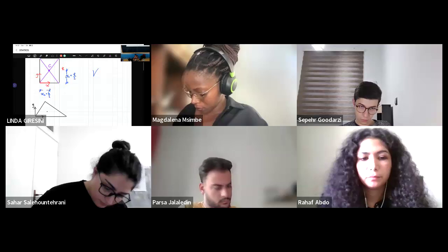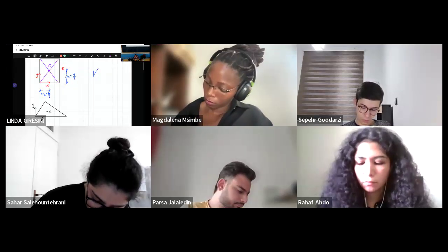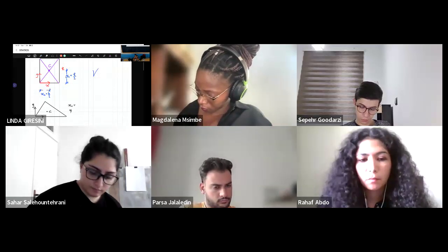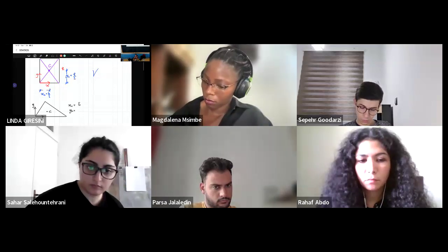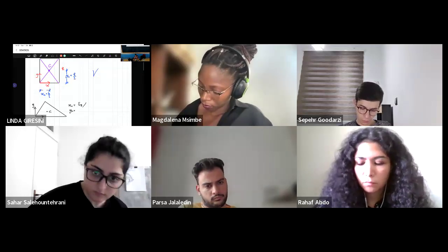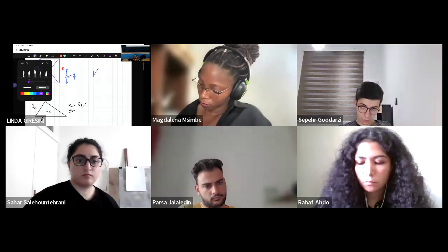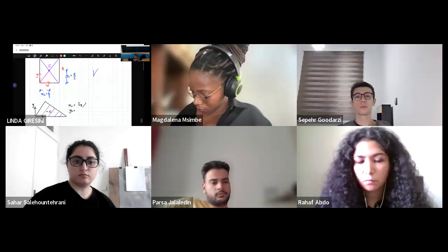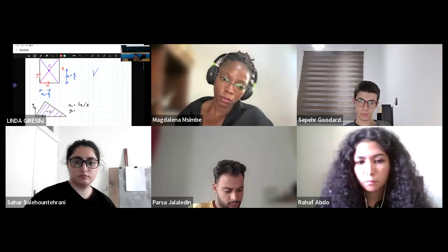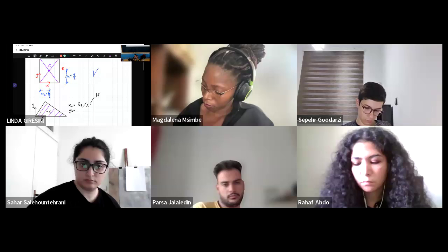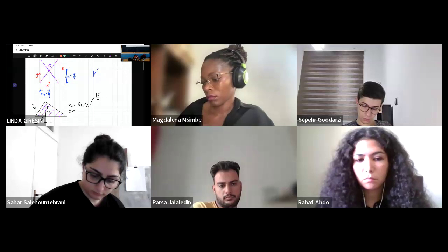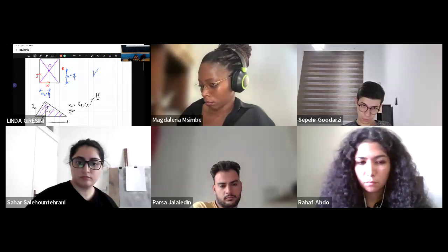So in this case, for example, your centroid will be here. So again, you have to write down XC and YC like static moments again. So for example, SY of this, in this case, it's a triangular shape, this one. So SY divided by the area of the triangle, which will be BH divided by 2 if the height is this one and B is the base of your triangle.